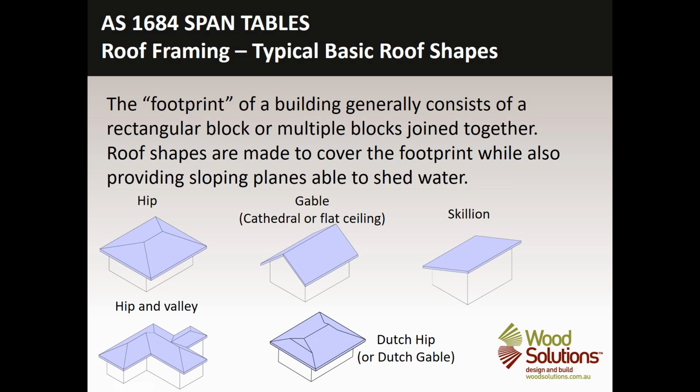I'll just quickly sketch up something like that as well. Do it over here. So let's say we've got a floor plan. Actually, I'll make this wing slightly shorter. Just do it very simply. Get a floor plan like that. We want to do a gable end, a hip end on that. So the hips go through there. Our hip will run from there. We'll do a minor hip here. So that's our major hip and our minor hip.